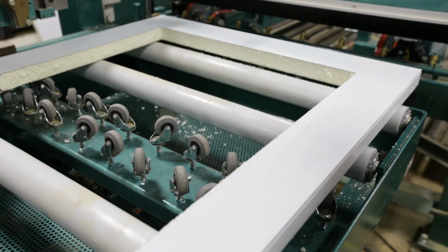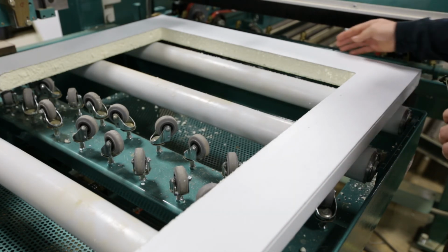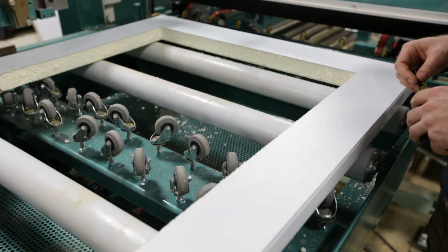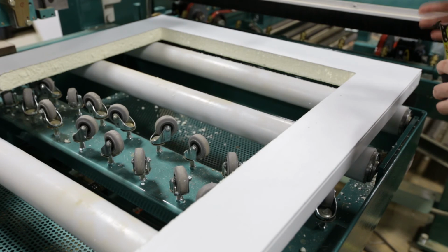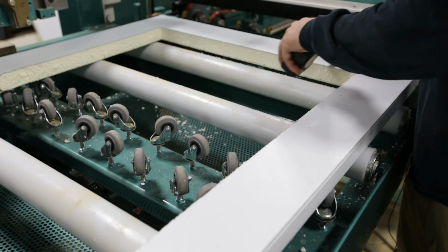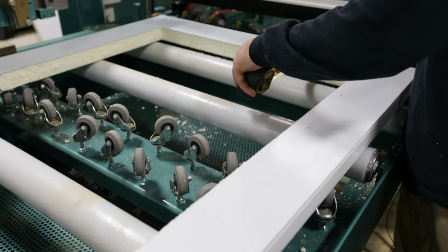Okay, so once your door has been cut, you want to check the dimensions to make sure that they're correct. First dimension we're going to check is the top down. And the top down is measured from the top of the door to the top of the cutout. And looking back on the PDF file that gives me my dimensions, this top down dimension should just be about a 32nd under 4 3/4 of an inch, 4 3/4 inches. So I measure here, and it's just about there.